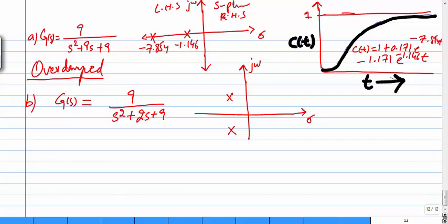Why? Because it will start decaying. It's not going to increase. Why? Because this is the power in the exponential. If the exponential is in negative sign, it shows that the time response is decaying. When the exponential power is positive, it means that it is growing. When something is growing, that thing is unstable. When something is decaying, energy is being removed from the system, so that system is going towards stability.